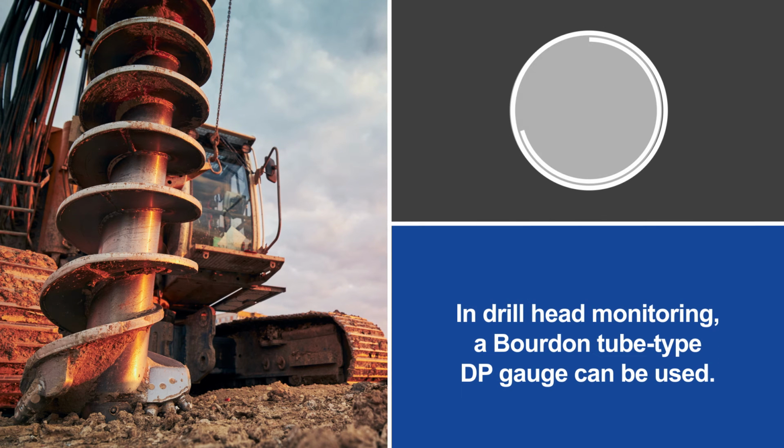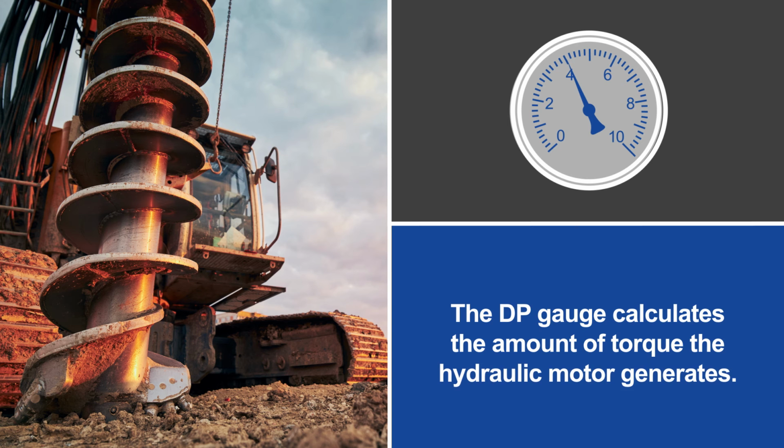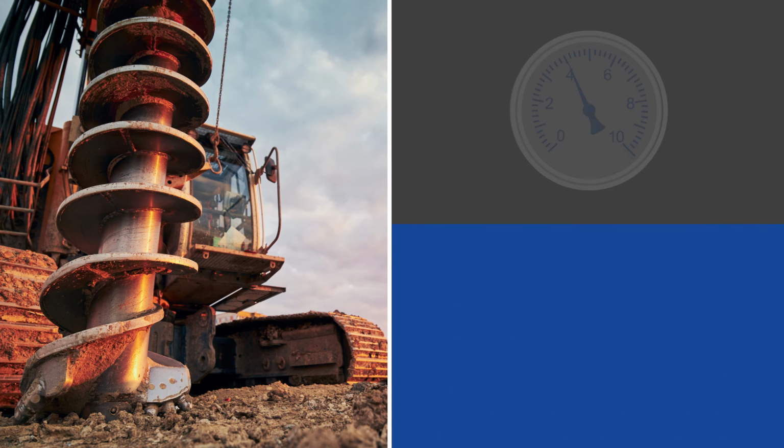In drill head monitoring, a Bourdon tube type DP gauge can be used for monitoring hydraulic motors by measuring the output torque of positive displacement motors. Through measuring a pressure drop, the DP gauge calculates the amount of torque that the hydraulic motor generates.